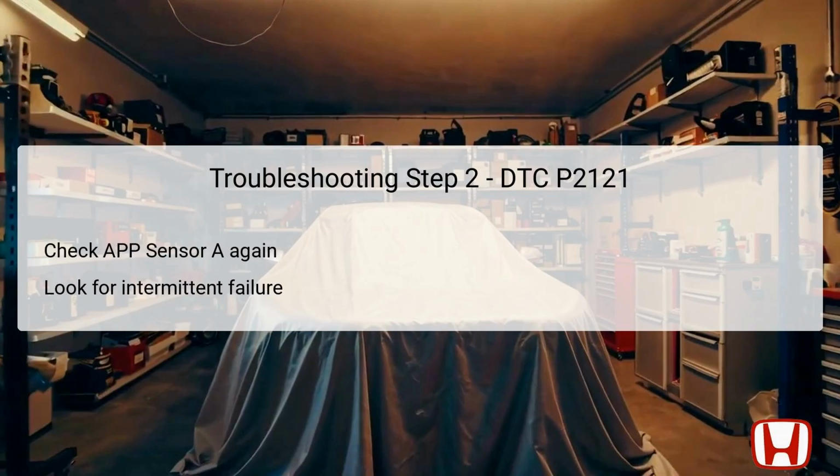In this second troubleshooting step, or problem verification 2, you will again check the APP Sensor A using the HDS. This time, look for voltages that exceed 4.99 volts. If the reading is confirmed to be within this range, the fault has been duplicated again, leading to possible damage or fault in the APP Sensor A.